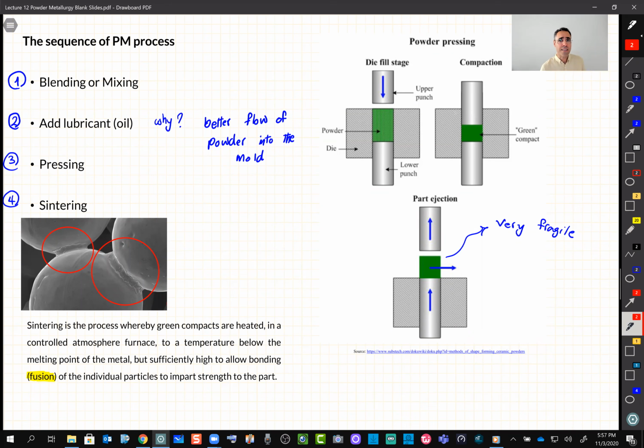With plastic, the main reason is because the conductivity is low. If you try to sinter it, some particles start melting, while nothing happens to the ones in the core. There is a particular process that uses powder plastic, but with a different approach. This process is mainly for metals. That makes sense. Okay, thank you.